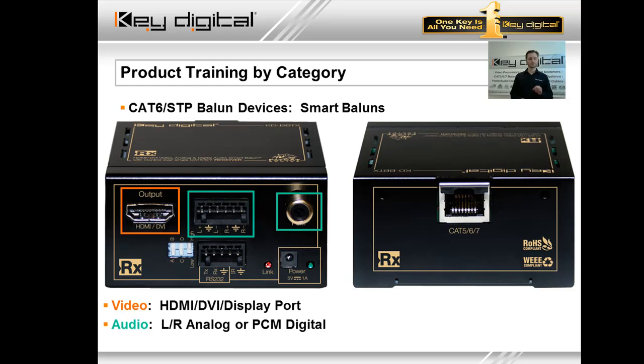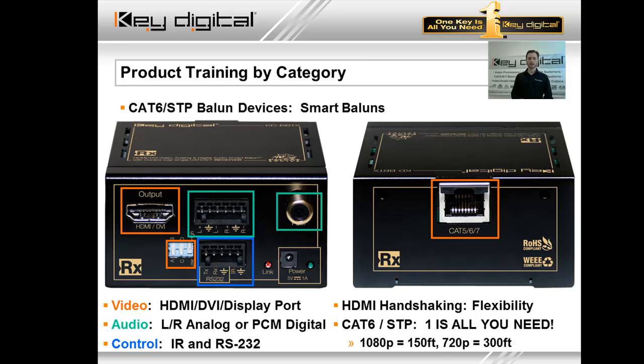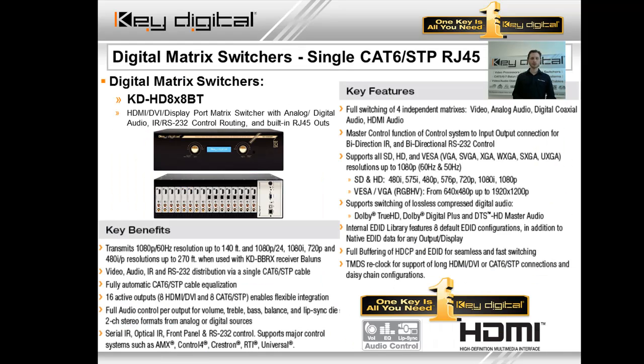Again, we're not violating HDCP here, so remember, if you're trying to extend an HDCP source and you'd rather go with external audio, not going to happen, okay? You're not going to end up with anything. Control on the Phoenix connector outlined in blue, IR and RS-232. Now we see that the matrix itself is a hub for your control system, and we'll show you in more depth exactly how that works in just a moment.